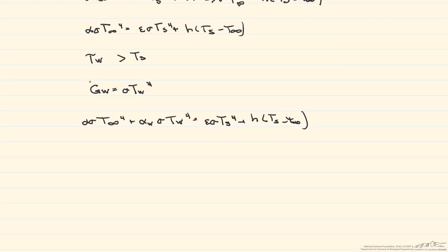Along with the question stated before, try to simplify or complicate things by asking yourself, is the surface opaque? If the surface is opaque, then tau is going to be equal to 0. Is there irradiation from somewhere else besides the surroundings?